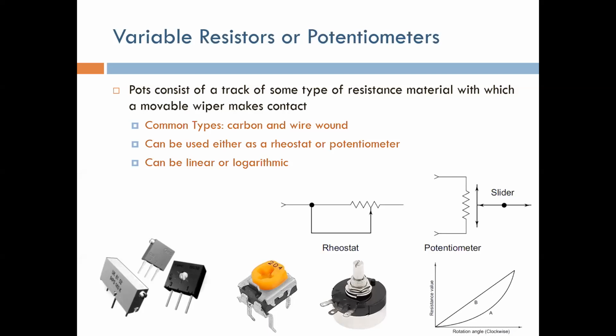Usually you use a logarithmic potentiometer so that you can increase in a manner that feels like, if you double it, you feel that it's double the intensity of the sound. So be careful when you're ordering a potentiometer: if you want a linear potentiometer, get a linear one, or a logarithmic one, and make sure that it's like that.